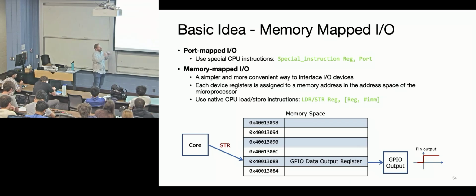We're only going to use loads and stores. You as a programmer now have to be responsible for knowing that when you're putting bits into particular registers, that has this other effect. But it's a very portable architecture, meaning that many people can repurpose it for other tasks. Intel architecture is only really going to be good at PCs or desktop applications because it's port mapped.